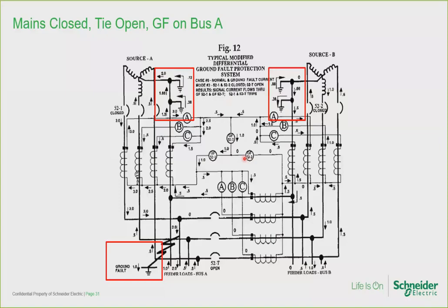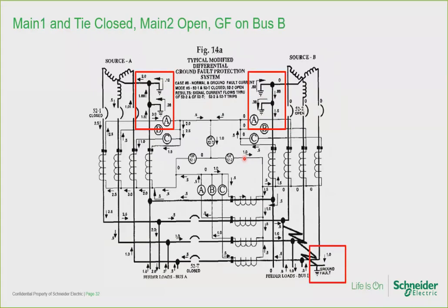If you perform the analysis we did on the previous slide, where you determine the primary currents flowing into the 12 CTs, then determine the secondary currents and total them up at the summing points where the residual currents are created, you will find that CT secondary currents flow properly into the Y-connected ground fault relays so as to trip only the breakers that need tripping without nuisance tripping any other breaker. I'm not going to burden you with any more analysis because this presentation is almost done.